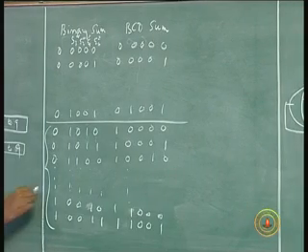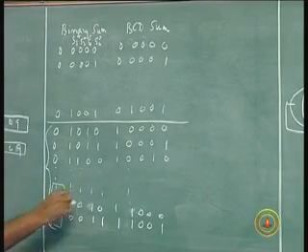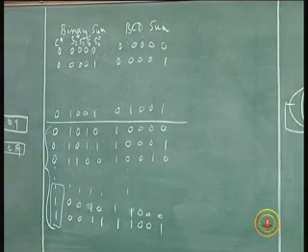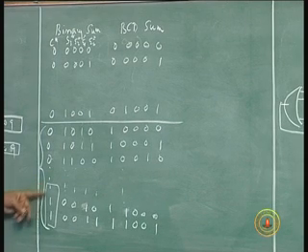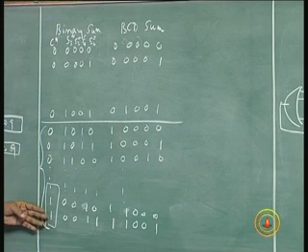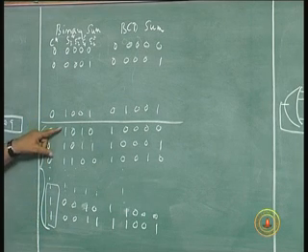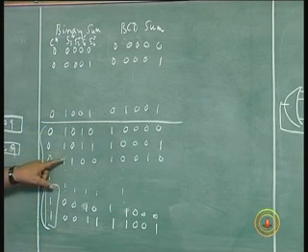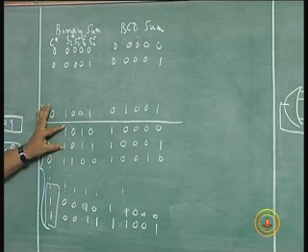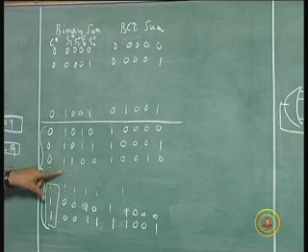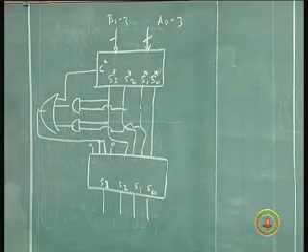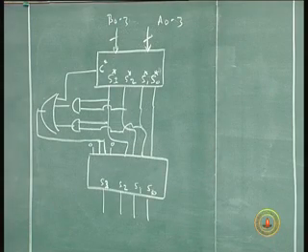Either this carry, which is the binary carry, this is C bar. So, I have to add 6 for all these cases where C is 1, or C star is 1, or when these 2 are 1, this and this bits are 1, or when this and this are 1. These first 2 terms are taken care of by this, then all the other terms are taken care of by these 2, and the last terms are taken care of by these 2. So, I have to add this; we will call this the final carry, which is what is required.